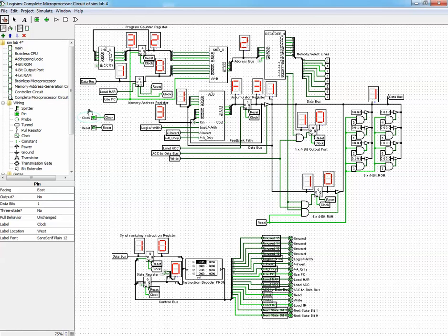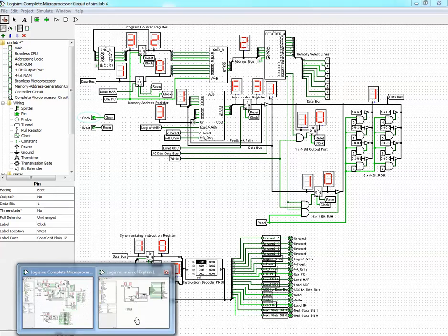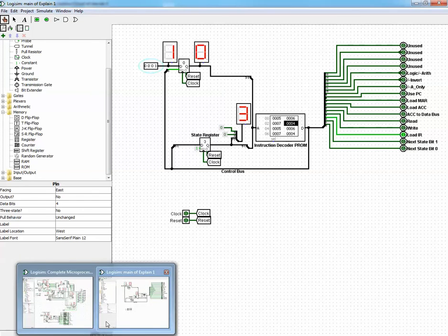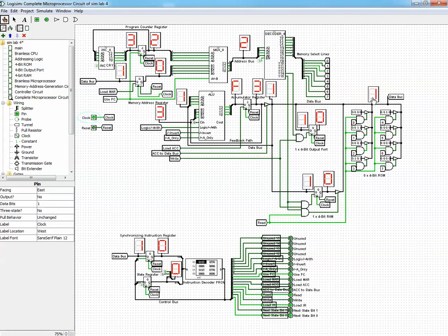So once you tick the clock, this one will pass to the input of this instruction decoder, which is the same as if you have written down here 1 and enabled this register using load IR. So we have actually enabled the register load IR by 1, and stored here a 1.